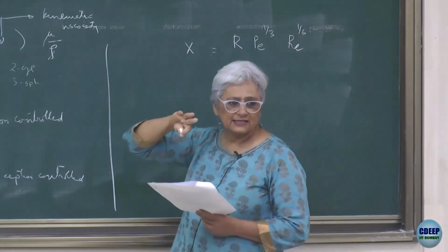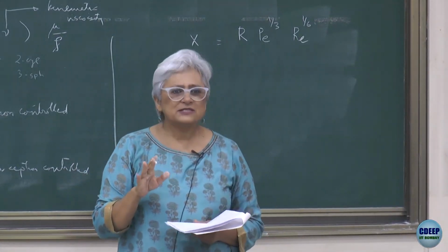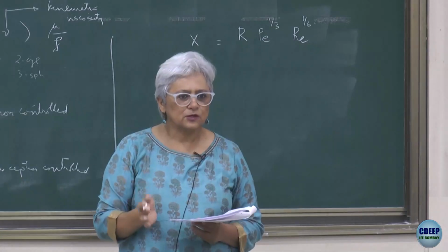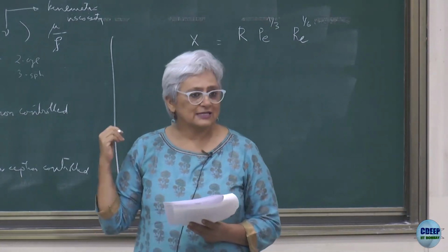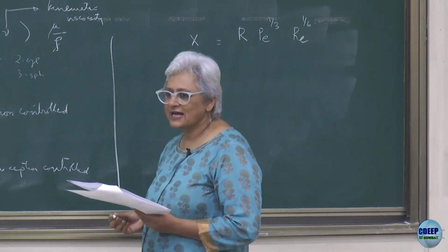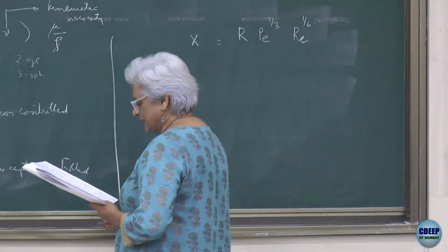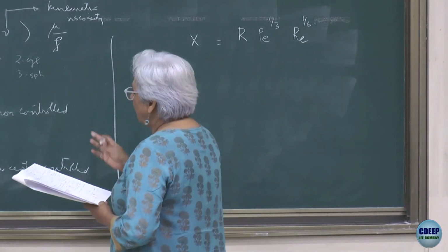So that Reynolds was stuck inside the A last time, and we said it doesn't vary much, it's almost a constant, but that's not the case here. So here there's an explicit dependence in the high Reynolds number case, and we end up with a Reynolds to the 1/6, right?